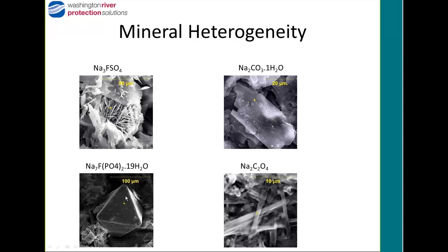And then, of course, particle size. I found a small one. This one is only 100 microns. These crystals grow to be several inches in size. Versus some of these needles, which on one axis are not very big. So if you think about the mixing behavior of this complex mixture, it's going to be different than if you have a single phase of spheres. And that complicates our prediction of mixing performance.